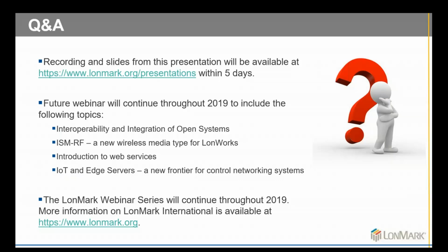So in that case, just to extrapolate a little bit, let's say you had a facility, a building or home that had HD-PLC running LON, and you also had another application running IEEE HD-PLC running some other protocol in the same environment, all running on the same power line. Could those potentially, using that ISP, interoperate or at least coexist without interfering with each other? Yeah, definitely they can coexist. As long as it is HD-PLC to HD-PLC, it doesn't matter if it's running LON or BACnet or any other protocol. Okay, well, that's great. So you could mix them.